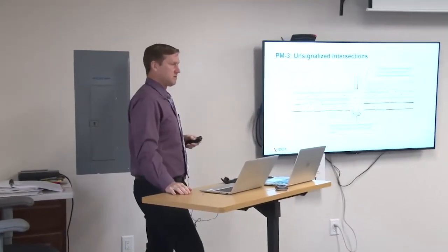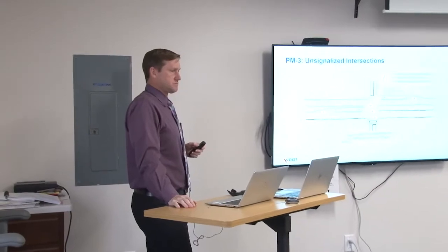And I would agree, definitely, but edge line, when it's necessary, maybe, very rare, but on a straight segment like this, why? Yeah, not on a straight segment, you're right, but sometimes you'll have, on a curve especially, a big, long opening. It's not a well-defined intersection. I guess we help to fix deficiency in geometry. But we know we cannot fix geometry with a pavement mark. Well, there's a saying that the best of pavement markings can't fix bad geometrics. So, but in some cases, it does help. Particularly, it's more helpful to do what you see there for the median. That is really more of a safety improvement. But where you need that additional guidance, you can carry that through, just like you could carry an edge line in front of a driveway, a local driveway.